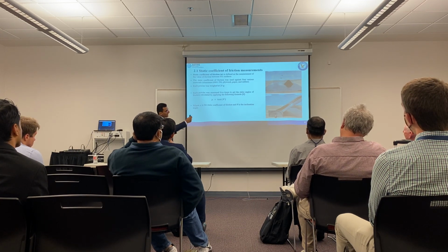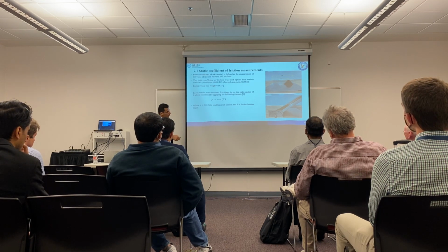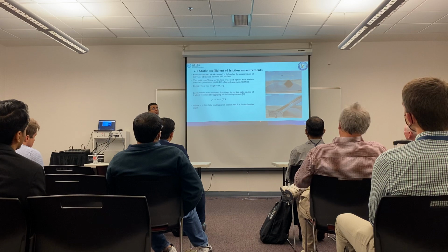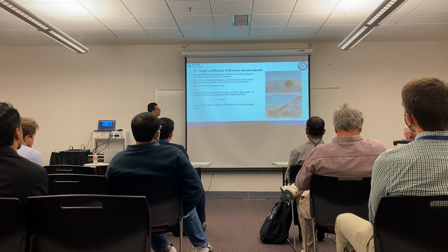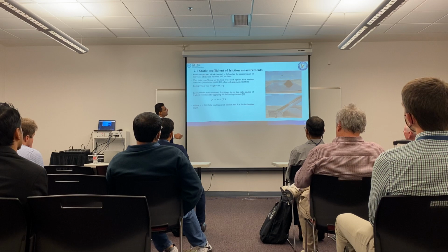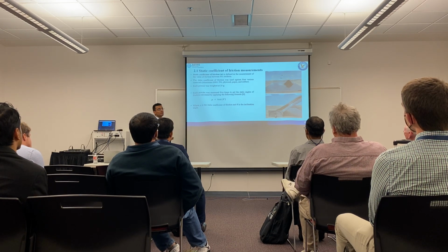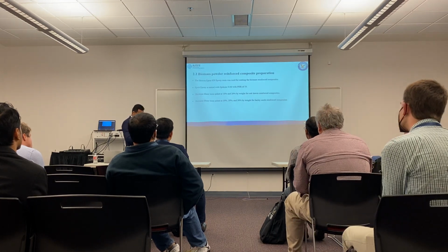Then we have a stand to fix the inclination angle. After that, we used this protractor to measure the angle for the static coefficient of friction. Then we applied mu equals tan alpha. For both the flowability and the static coefficient of friction, we used the same amount, 25 grams per test.